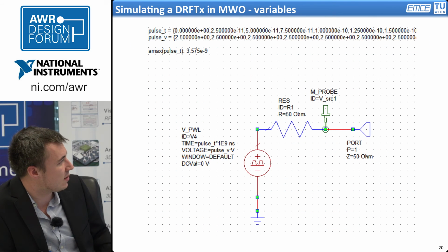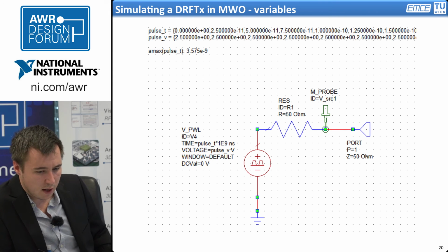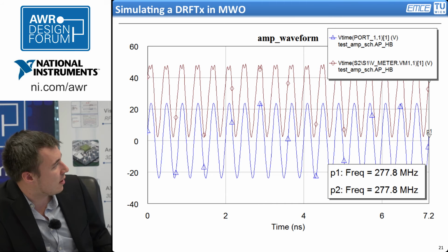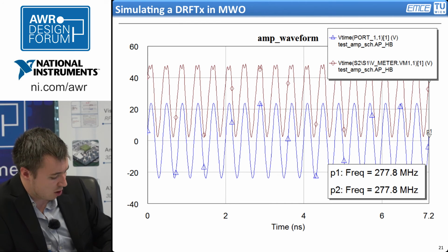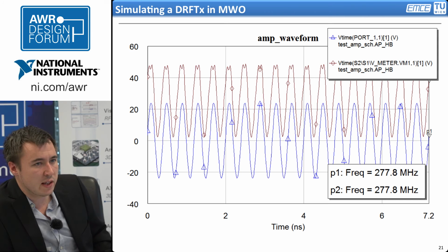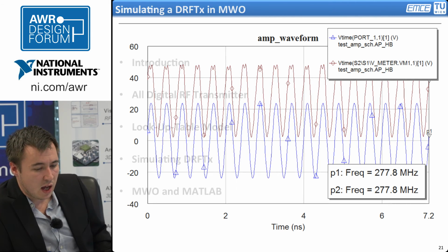This is just the way I built the arbitrary waveform port here. And if you now let the simulator run, you get these waveforms. Here the blue curve is showing just the output waveform, and the brownish line at the top is indicating the intrinsic voltage waveform at the intrinsic transistor, which was the parameter we were mostly interested in.